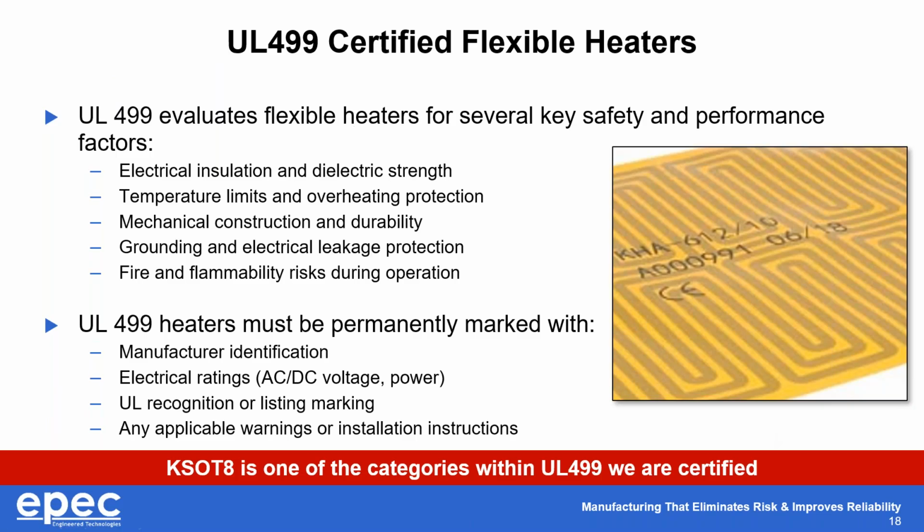As I mentioned before, there are several tests and performance criteria that UL 499 covers. The first is the electrical insulation and dielectric strength of the heater. Next would be the temperature limits and any overheating protection circuits that are built in. Next is an evaluation of the mechanical design and its durability.